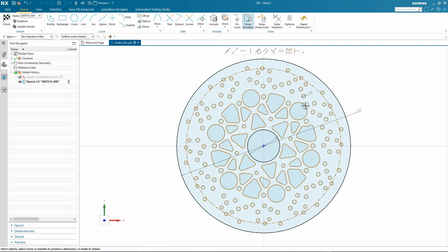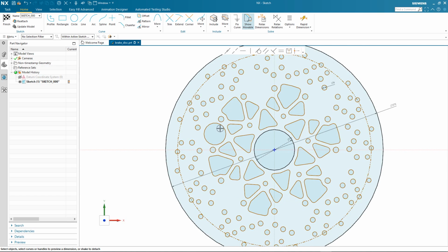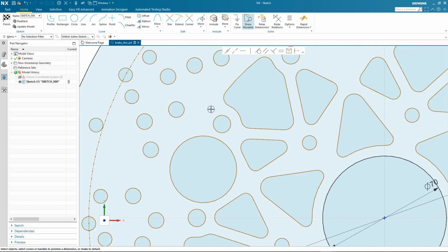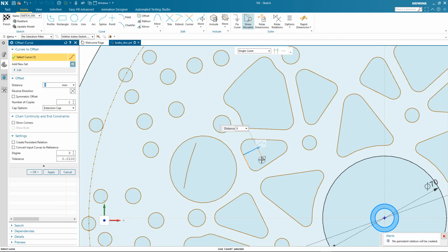So my final task will be to change one of the internal profiles. So I'm going to delete the ones I don't want and just concentrate on the one that I want to modify. I'll use the new rotate drag option in the sketch tool to dynamically copy one of the curves from one of the other profiles that I can use in my new modified profile.